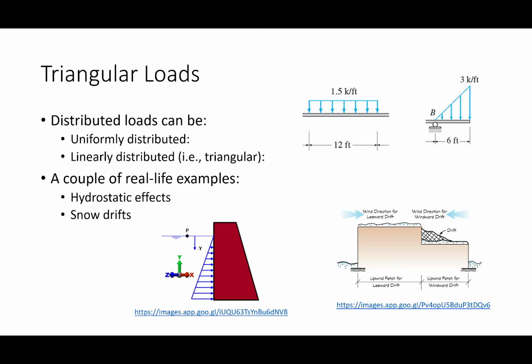Another area that's more directly applicable to structural engineering is snow. Has anybody ever been on the roof of a commercial building, a building kind of like this one? Are they hyper sloped or are they kind of flat? They're usually kind of flat. They're sloped a little bit because they have to drain rainwater and whatnot. But usually it's kind of flat. You've got maybe gravel or a neoprene rubber sheeting on top, and then there's a little curtain wall, about maybe yay high, and that's what restrains the activity on the roof.